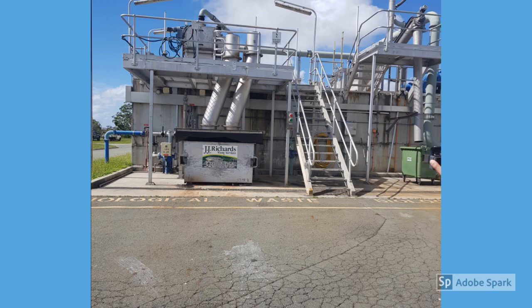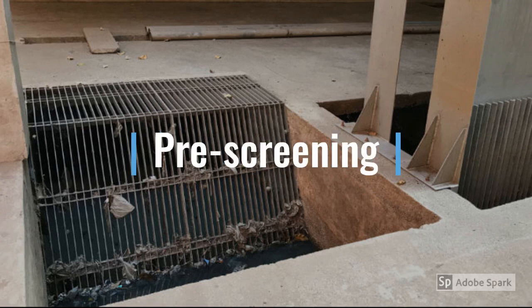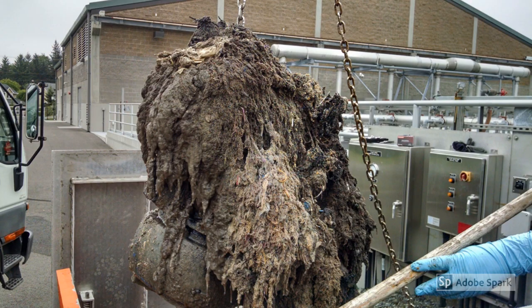Here, the raw sewage is pre-screened for solids and materials that cannot be processed or that may potentially block processes or pumps further along the chain. Unfortunately, as informed by one of the technicians, much of this screened material, referred to as RAG, is material that is not designed to be flushed into sewer systems, and a large proportion of this waste happens to be sanitary products. This pre-screened waste can amass to around 400 to 500 kilograms per day.